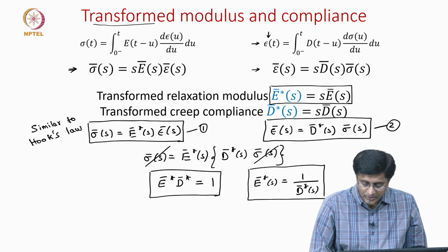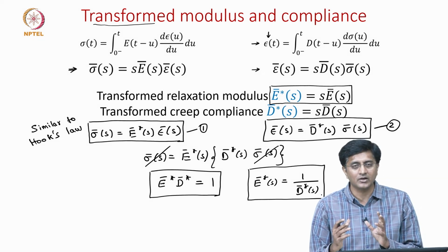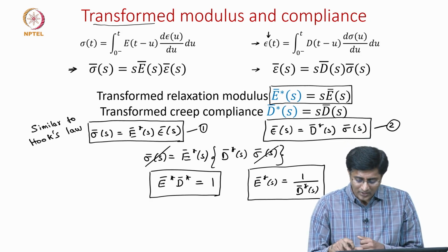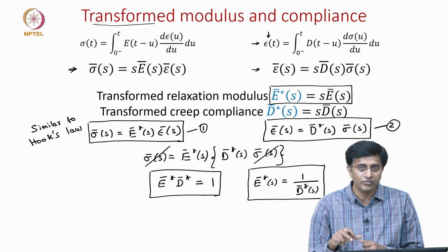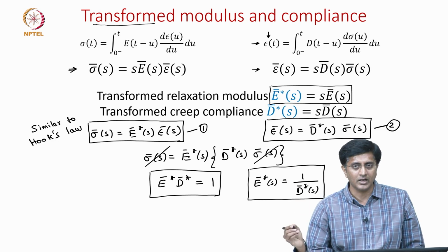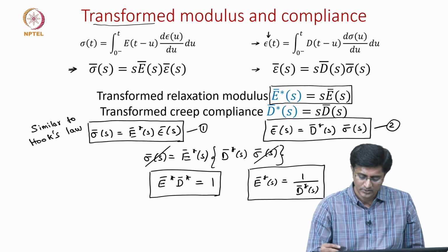So, the reciprocality between the modulus and the compliance which we have seen for an elastic problem, we can see it for a viscoelastic problem. The difference is we are seeing it in the Laplace domain, but not in the time domain.